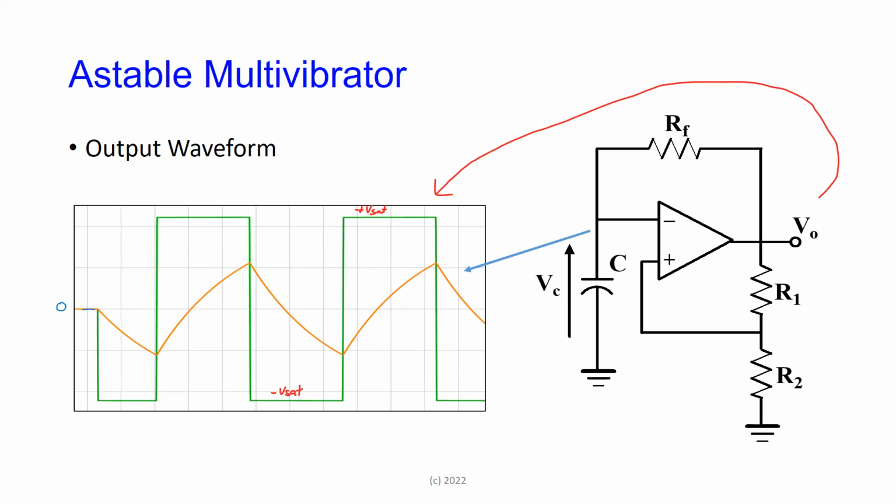But because of leakage currents in the circuit, remember all of these circuits are not ideal, there are small currents that will be flowing around. The voltage on the capacitor starts to change. It starts off at 0, but because of small leakage currents in the circuit that exist just because the circuit is powered on, this voltage now changes.